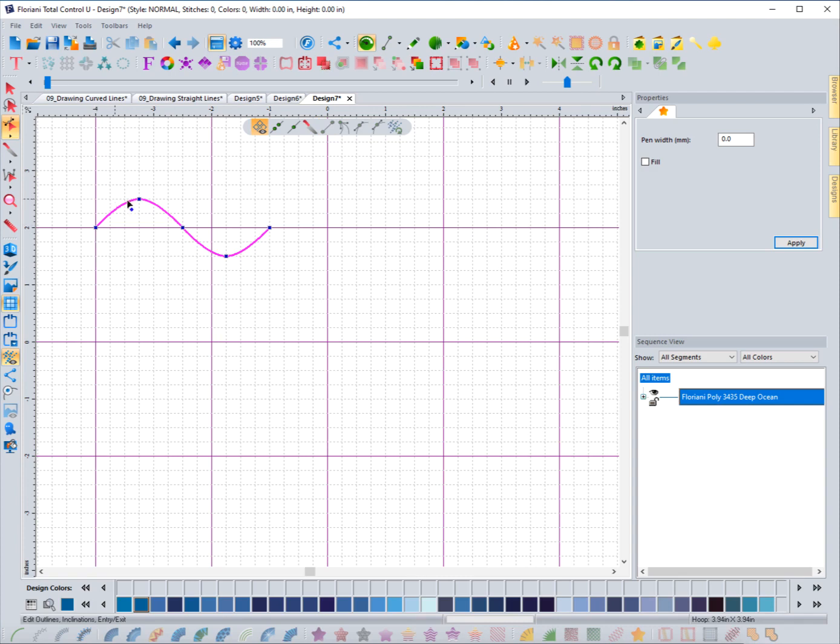So a lot of times if you're wanting to create something that's like a wave that goes straight across, the best way to do it is just to use the grid and create a bunch of points and then change the ones at the top, the ones along the upper line and the lower line to symmetrical, keeping these all straight lines, not changing these points here, but only the ones on top and bottom. And it can allow you to create a nice little wave or a line that bends, that's repeated.